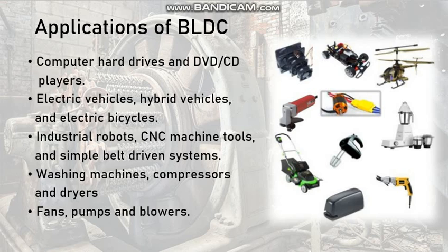Other than that, BLDCs are vastly used in industrial robots and CNC machines as well because of the precision and position control due to the feedback mechanism by the Hall sensor. High torque also makes them an ideal choice in water pumps or power pumps and fast fans, as well as washing machines and other such devices.